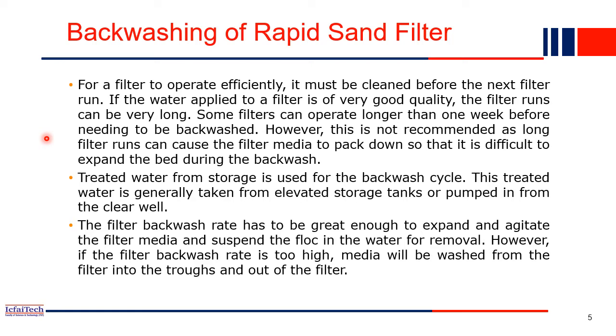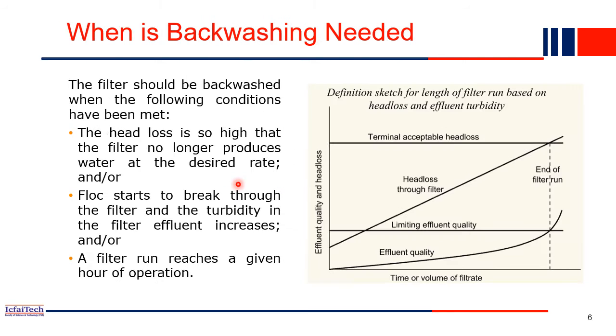The pollutant will be deposited in the filter medium. So for backwashing we also have to send the clean water at a very high speed, so that the particles present in the sand bed are suspended and ultimately washed off. So that is the backwashing of a rapid sand filter. You have seen what the working mechanism inside is.